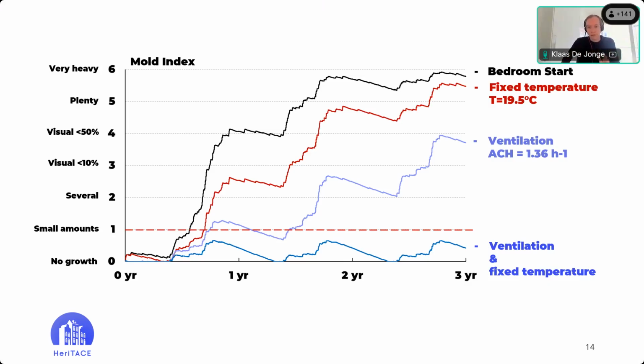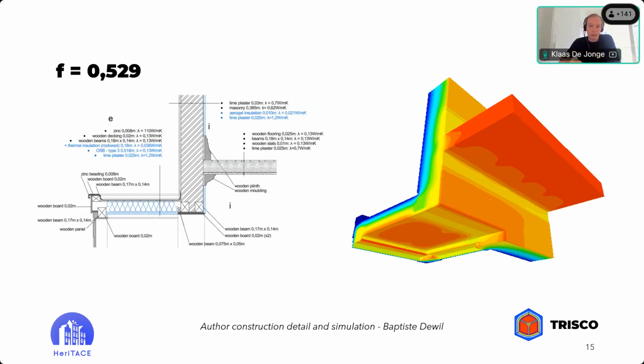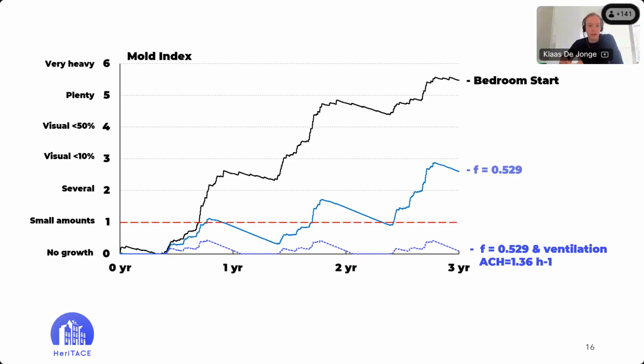So let's look into something in between, because actually there are smart and not as invasive ways to fix these thermal bridges. What you see here is the same detail, but with some insulation in the right spaces, with very low impact. And actually you can already get to a temperature factor which is 0.2 higher. So it's much better. But looking at the results, not enough.